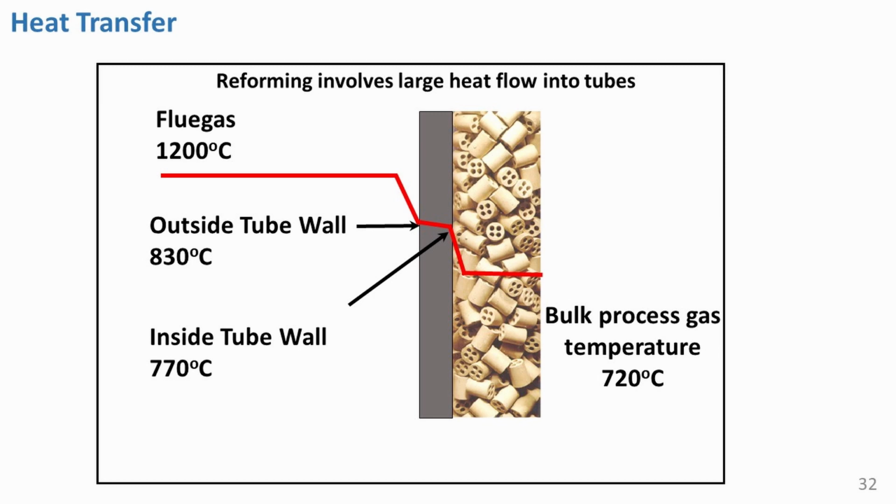A flatter axial thermal profile through the catalyst bed can be achieved by using a high thermal conductivity carrier, such as monoliths or foams, leading to heat redistribution along the catalyst bed with a consequent higher hydrocarbon conversion. In addition, the highly conductive support ensures a more uniform radial temperature profile, thus resulting in better heat transfer, a reduction of hot spot phenomena, and very stable performance.